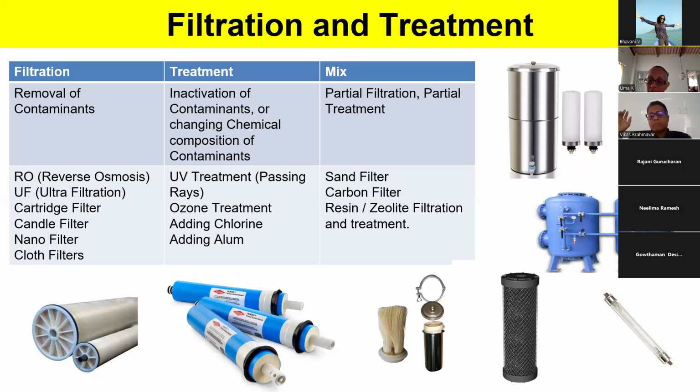UV system is a point of use system, we should be aware. If you take the UV treated water and put it in a tank, after 8 hours you will still have bacteria. If you take the water within 6 to 8 hours, then UV treated water is okay. UV is ultraviolet. I'll come to UF a little later. Ultra filtration I'll come to later. That is a filter. UV is a treatment.